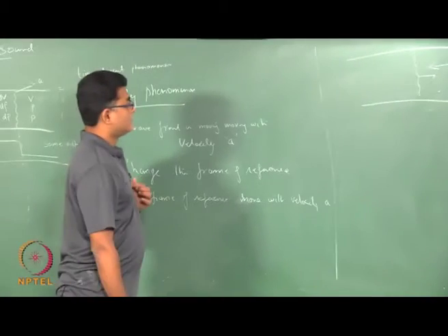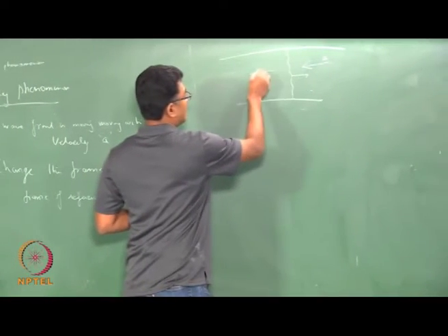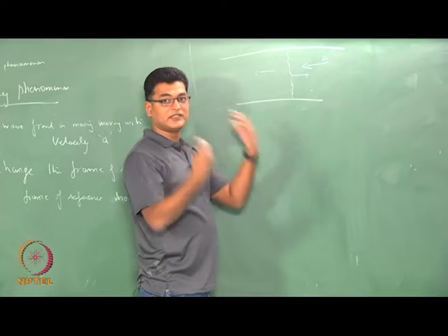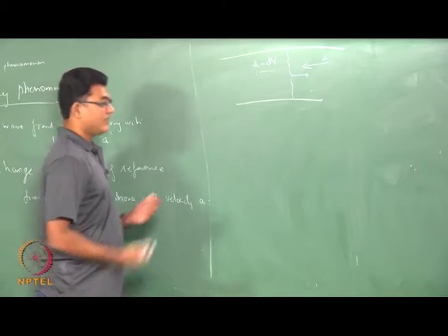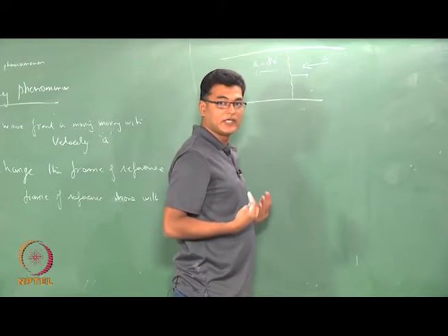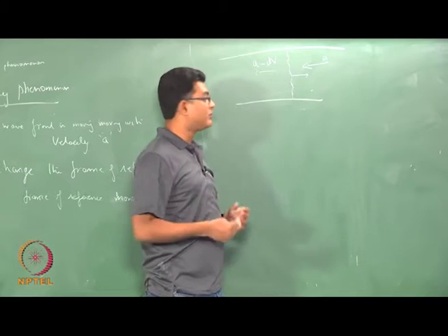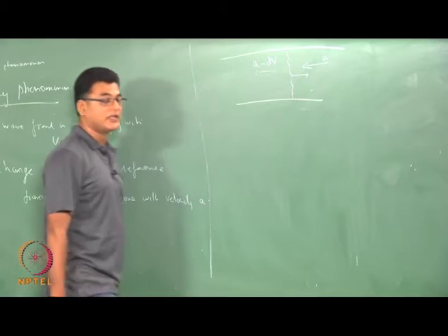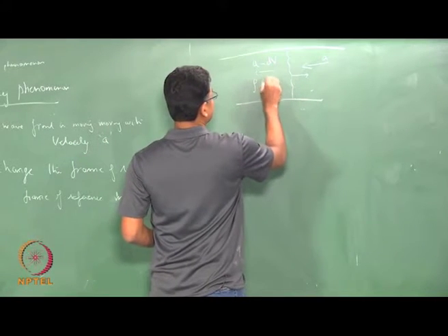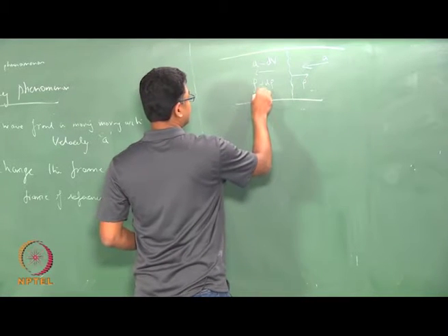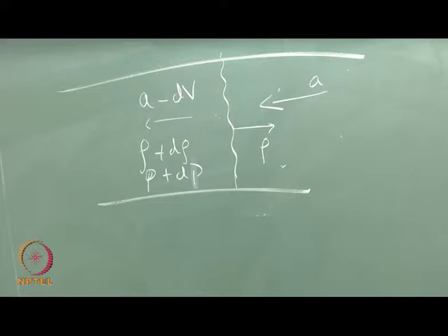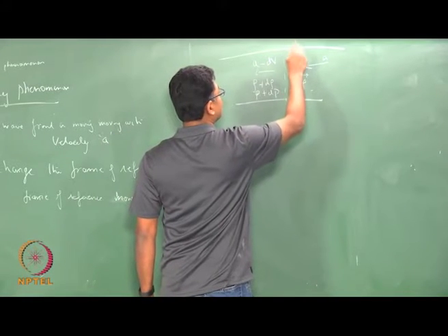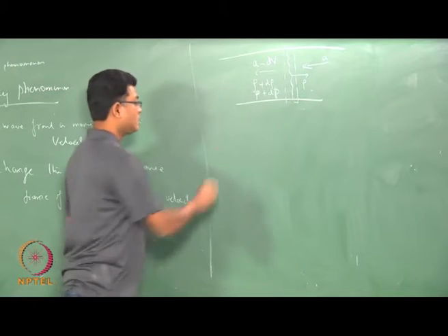What about this? I would see my fluids behind me receding with velocity a minus dv. Okay. So, I would see my fluids coming and hitting me at velocity a, and I would see those fluid particles receding from me at velocity a minus dv. The thermodynamic quantities do not change. So, my rho plus d rho is the same as previously, before my change in reference. Now, what I do is I take this as my control volume, a thin region around the wave front.